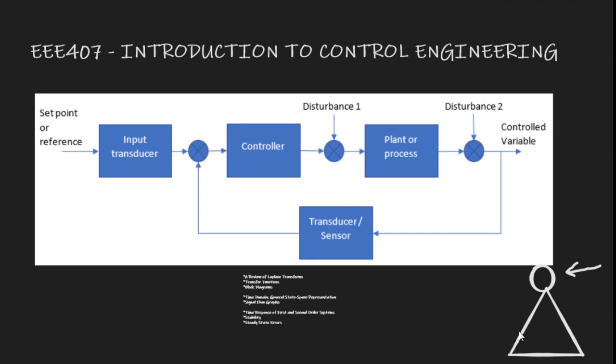This system we say is unstable because a small input, now I don't want to get too technical at this point, but a small bounded input is providing an unbounded output, that we don't have a limit to what the output is, literally. Like I said, imagine the sides are infinitely long. This thing will just keep on falling until a different input comes to stop it, which could be, if it gets to the ground, action and reaction equal and opposite, then that will now stop it from rotating any further. But that is a separate input. Based on this single input, small push that we give it, we have an unbounded output. This system we will say is unstable.